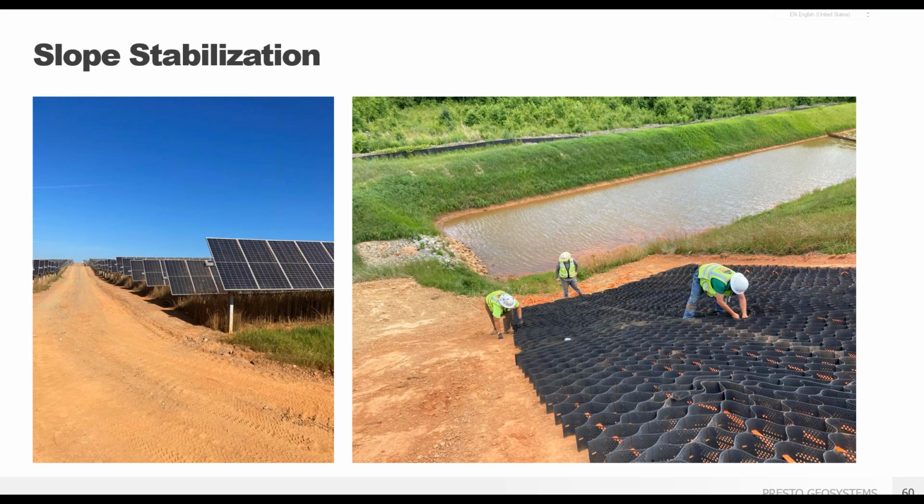This is a vegetated slope project at a solar farm and allows us to show some great step-by-step install pics while pointing out some best installation practices with ATRA-Tendon clips. The solar site included a sloped area leading to a large detention pond for stormwater management. GeoWeb helps stabilize that slope and control erosion.